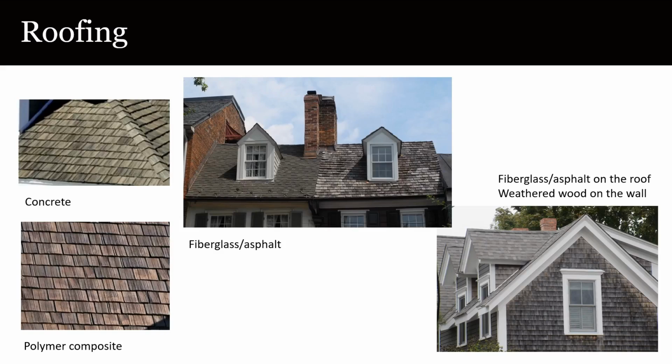Because wood is a weathering natural material that tends to have a good bit of subtle color variation, choosing a substitute that is consistent with the weathered color of the wood without being too uniform in color will probably have the most convincing effect. Because of the fire risk of wood shingles, even if treated, the justification for using a substitute may be more readily made in a high fire risk area, especially if other risk factors to the building are being addressed. Most substitutes can have a Class A flame spread rating, if not being outright non-combustible.